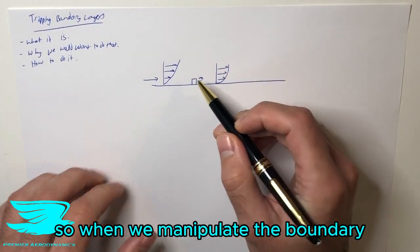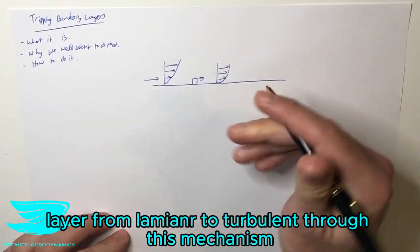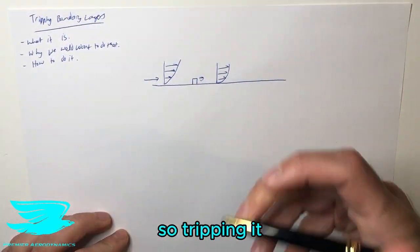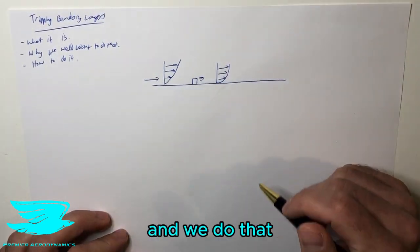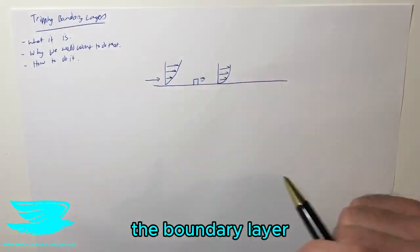So when we manipulate the boundary layer from laminar to turbulent through this mechanism, that is called tripping the boundary layer. So we're tripping it from laminar to turbulent, and we do that by introducing a lot of turbulence from this object in the boundary layer.